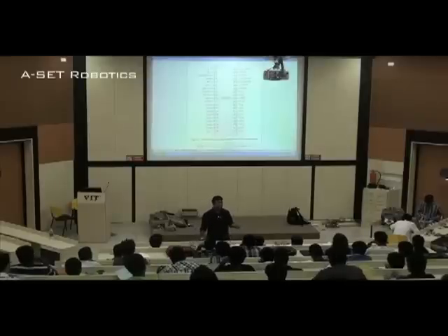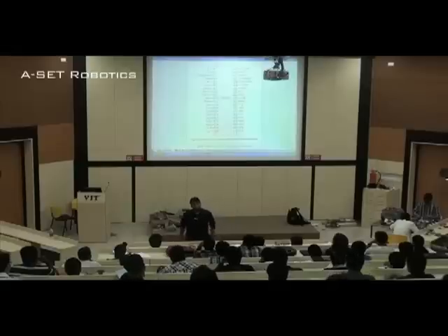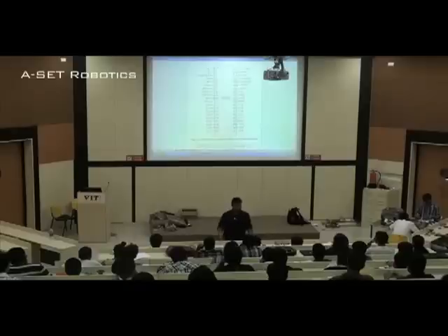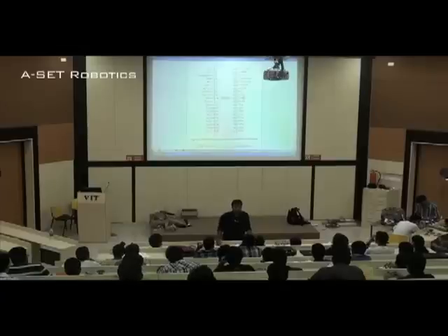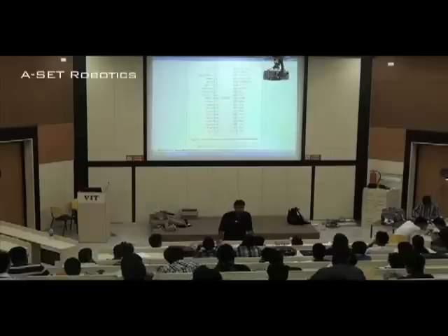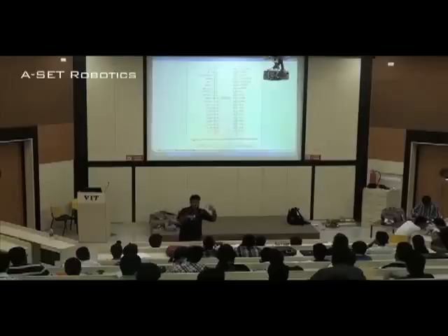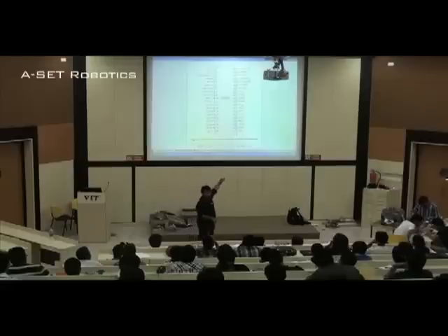No. So when we say that a microprocessor is working at 3 megahertz, does it know at a certain point of time what its state is, or how many times it has to work? We have to give the signals that state. How will it happen? We have to give a clock pulse. That clock pulse will synchronize the working of a microprocessor, and this clock pulse would be given by X1 and X2.